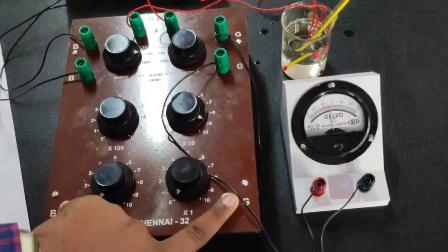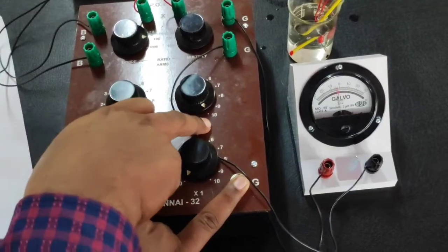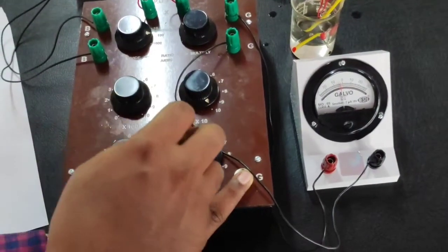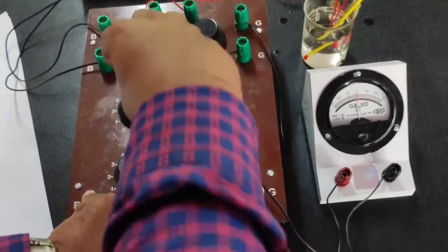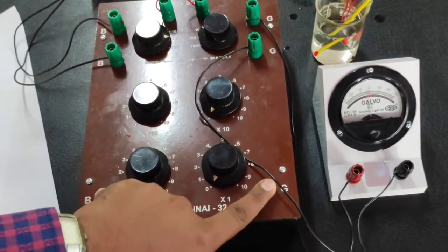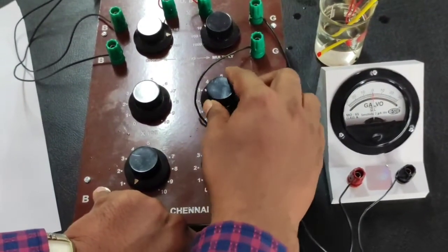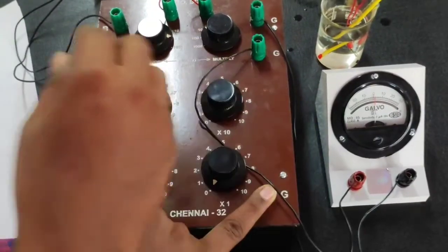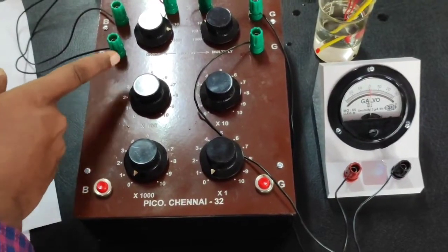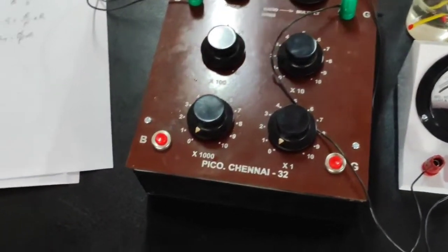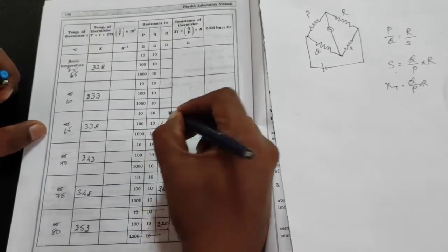There is a deflection. So I have to increase the resistance on this 10 dial, but this is a maximum value. So we can reach the maximum value here. So just reduce this into 0, 10, and just increase the 100 in 1. So now the same position will be here. Again, you have to increase this 10 resistance. And at a particular position, we have null deflection, and find out what is the corresponding resistance here. So 450. So for 65 degree centigrade, we got 450 on your R dial.